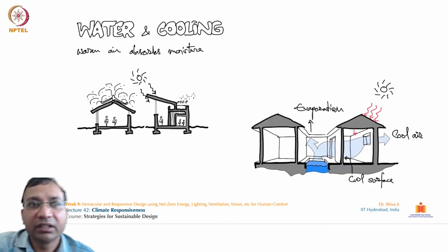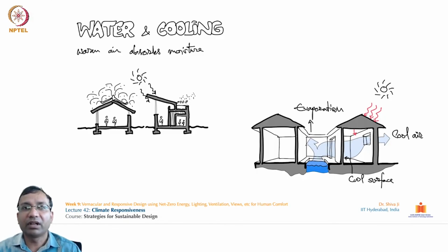Similarly, for shading and cooling effect, how these pergolas and other sunshade devices can be installed in which parts of these buildings, and how this can be maximized for efficiency. You can see here this double roofing treatment is given, to minimize the overall heating in the bottom floor. So there is a buffer area of air only, because air is one of the best materials for thermal insulation. This air is also naturally trapped over here, creating a buffer zone.